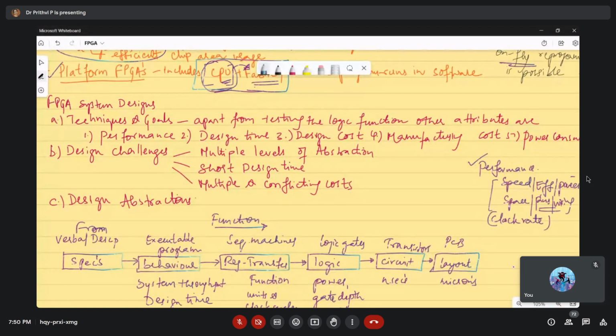And power and energy: if we are measuring, why do we need this power consumption analysis, to find how much power it is consuming? Say your complete circuit is based on a DC supply, like when you will be using batteries. Using a battery, what battery life will it give if you are using that circuit? That sort of analysis you have to perform. Even if a system is not completely used, with only partial use or in idle condition, some battery draining also happens. That sort of analysis has to be performed.